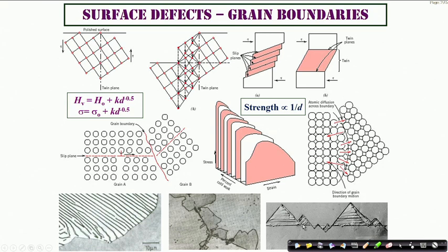The boundaries can take very typical shapes where it could be non-faceted or curved, or it can take a shape which is very geometric and flat. And such flat and geometric boundaries arise for one set of crystals under one set of conditions, whereas such curved boundaries can also appear in other kinds of crystals. And the reason why the shapes are different is principally attributed to the surface energy, the interfacial energy associated with them, which is in turn related to the crystals and crystal structure that we are dealing with.